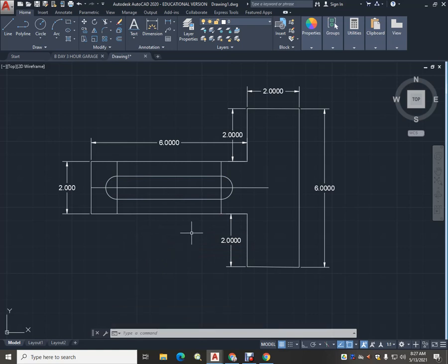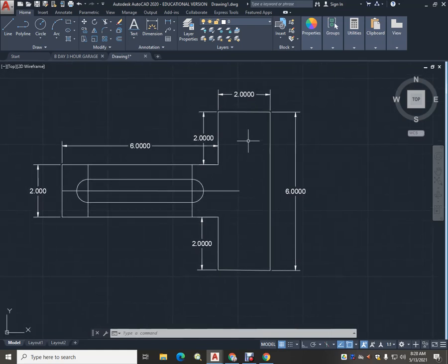We'll want to go back and put in our center marks. So now let's work on the two diameters that we want in this particular place. Let's do the same thing. Line, and we want to find the middle point of that. Or we could do an offset. We did an offset of 1 inch, we could do it that way. MID works.